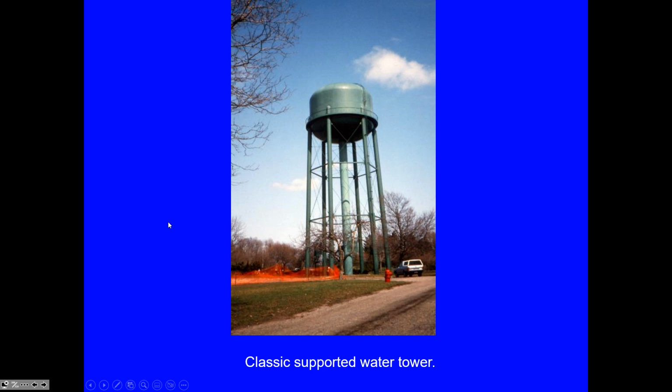The other advantage of an elevated tank is that it provides consistent pressure to the network, whereas if you're providing pressure with pumps, the pressure only exists as long as the pump is on. And during periods at night, for example, when the demand is low, you don't necessarily want a pump running that is a pump you'd use for the maximum part of the day.